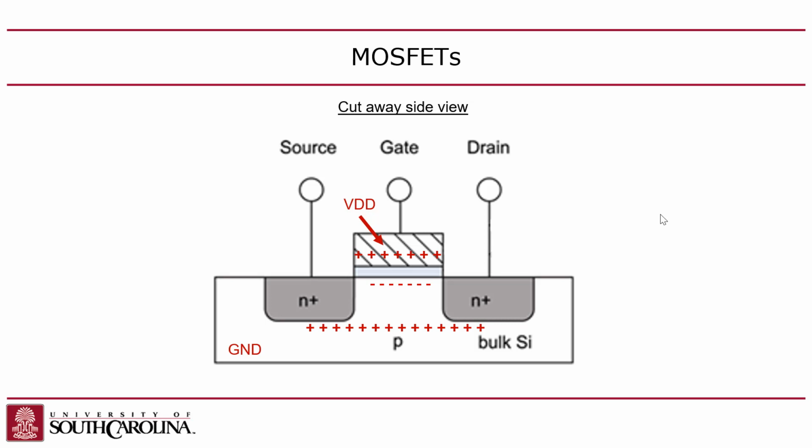That charge will attract electrons, which are not the majority charge carriers in p-type silicon, but they're minority charge carriers. Again, that part I've never, it's weird. Like how's that? The minority carriers are in there. They'll get attracted to the channel, and you end up with a channel. The channel is charge carriers that are forming under the gate. And that will turn this transistor on, and you'll start to conduct from these two terminals, right? So it becomes an electronic switch, right? And this is, of course, what enabled all digital electronics. I mean, prior to this, you had to use a vacuum tube to get this effect, right? Which was like a light bulb, essentially, right?